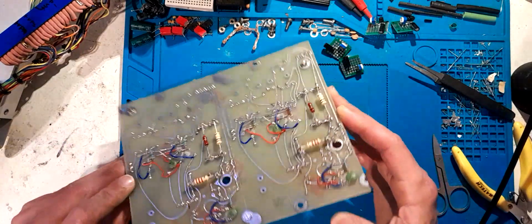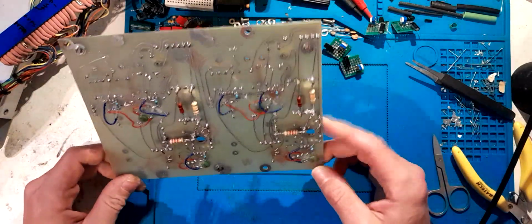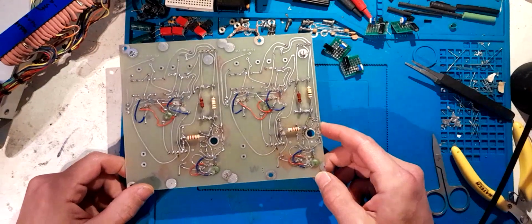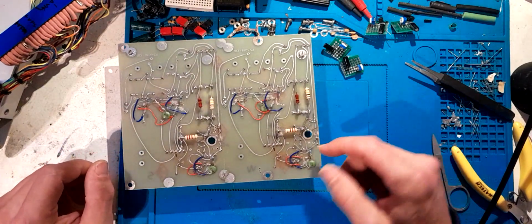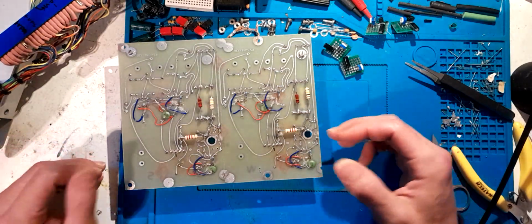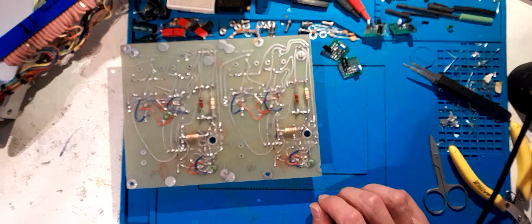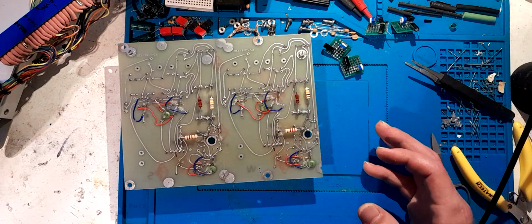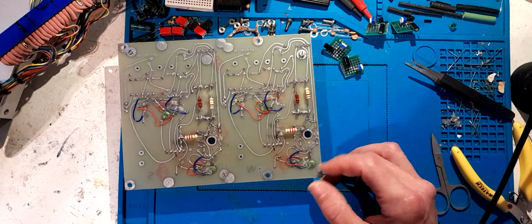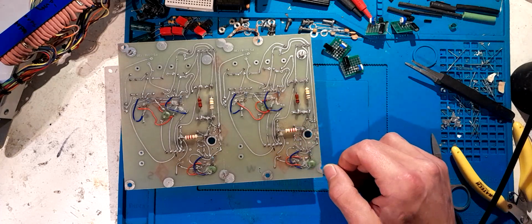If not, I can always put them on the back of the board. There's plenty of space on the back. But the main reason I've done that and not put the capacitors on yet is so that I can tack them on the back. If I'm experimenting around, I'm not going to have to keep desoldering and ruining traces. I can just tack them on, untack, you know what I mean? And once I've got the correct values dialed in, then I'll mount them through the two holes I've drilled and the two pre-existing holes where the Zener was.